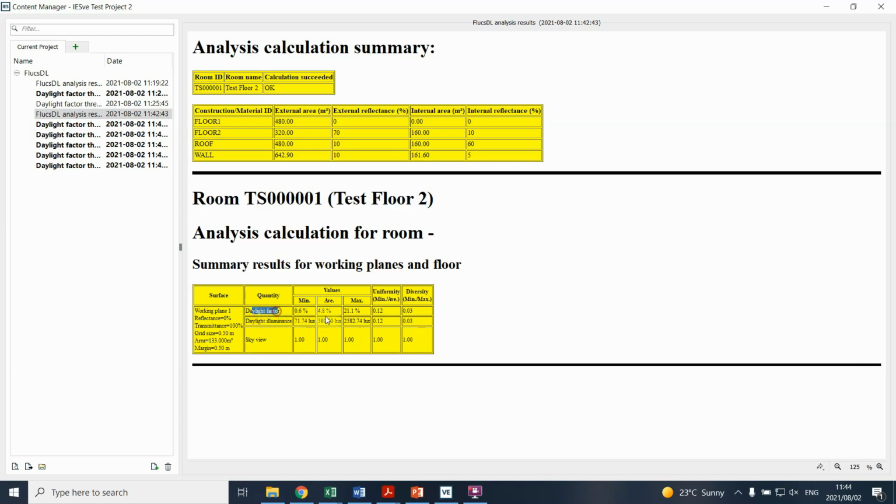If you look at the general daylight factor, we've got an average of 4.8%, a maximum of 21%, and a minimum of 6%. What that means is generally we're about 5 in terms of daylight factors. And a daylight factor of 5% is accepted. It's actually quite good.